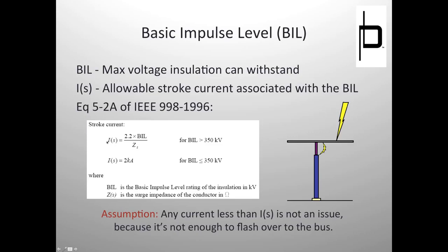Now that stroke current would be the stroke current that just causes flashover of your insulator. Any current less than that, we're not worried about, because your insulator will absorb it. It won't cause flashover. So any current less than that, we're not worried about.